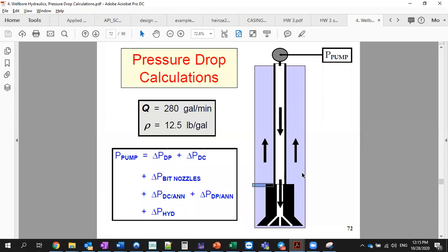So in that case, if you are in the annulus, you basically consider the hydrostatic pressure at that point, whatever length of fluid is on the top of that point, in the annulus, plus friction pressure loss within that section again, right? So you calculate the annulus pressure loss from the surface to the point of interest that I ask you, and you add that number to the hydrostatic pressure at that point, and that's it. That's your pressure at that point, right?